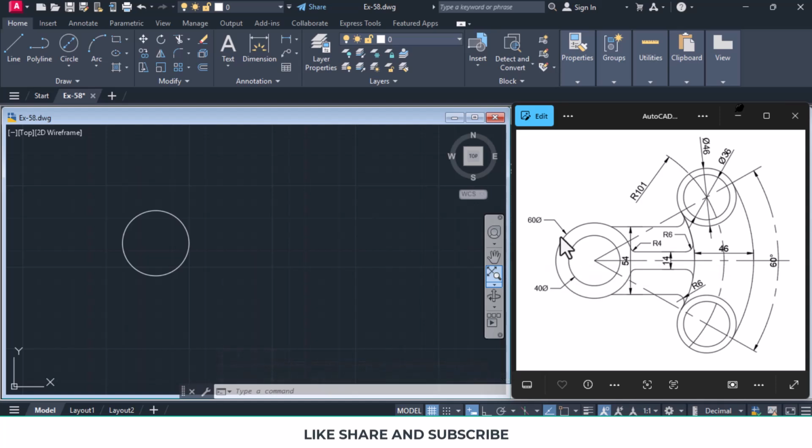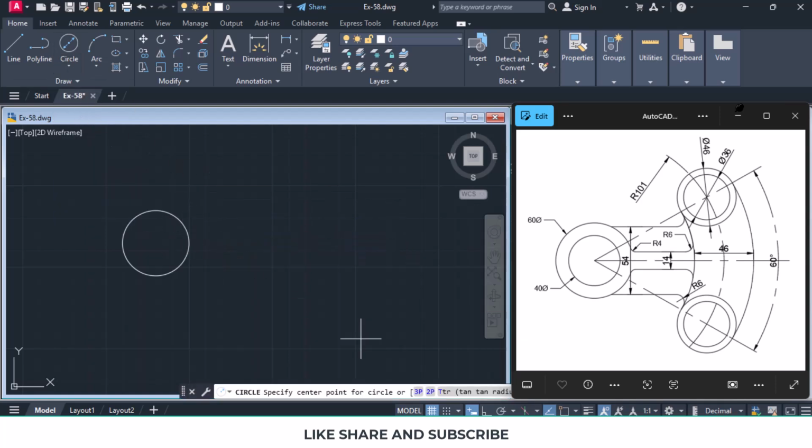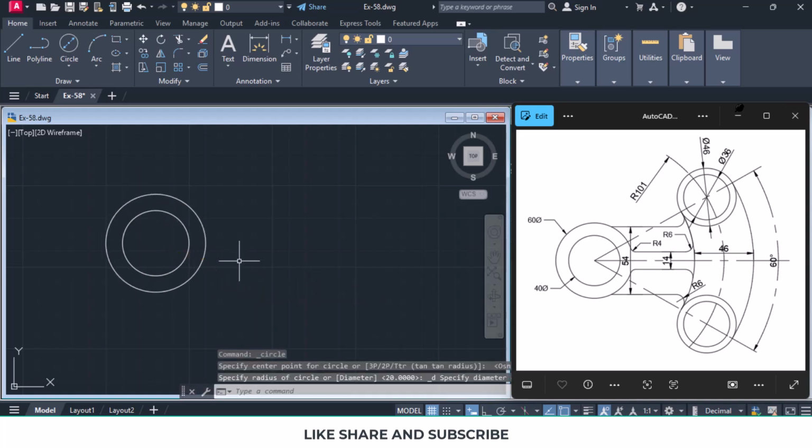Now we want to draw the outer circle of 60 dia. So again circle center diameter and then we turn the snap on, so we get the center point and we give the diameter as 60 units and hit Enter. So the outer circle of 60 diameter is now ready. Now we'll draw this line. It can be of any length, but the angle which we'll give is 30 units because this whole is 60. So this angle is 30 units.